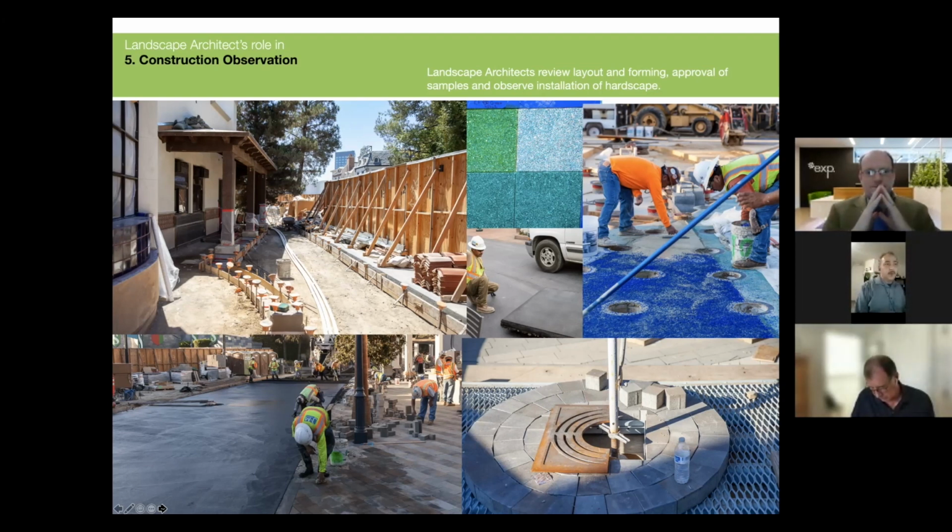The image at the lower right shows a mock-up of the assembly used for the trees planted along the street. Now, due to a high volume of foot traffic in the park, it was very important to maximize the amount of paving under that tree. You can see the metal grate covers the entire tree pit. The pavers sit on top of it, and the metal guard finishes and hides the edges of the pavers.